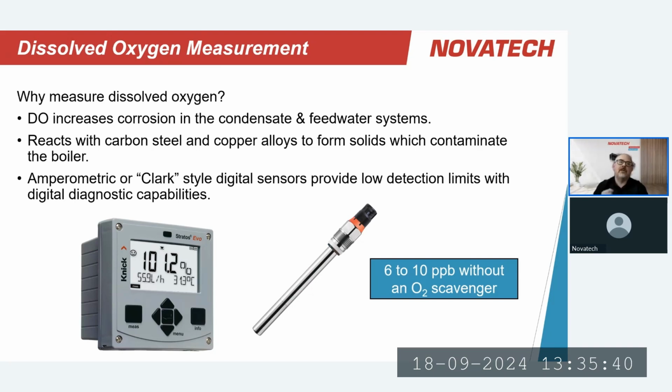So here's where an analysis such as a TOC measurement would allow us to see that we've got something coming through, we need to take action, our heat exchanger tubes are leaking, what are we going to do about it, and take corrective actions. They're not talked about in the standards from EPRI and all that. They're very much focused on power generation, but the reality is we generate steam for other purposes as well, and that's where those types of measurements may come in handy.